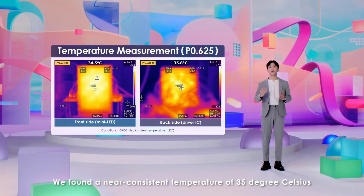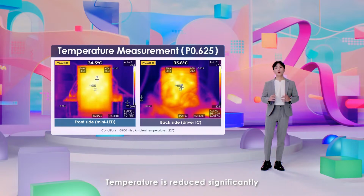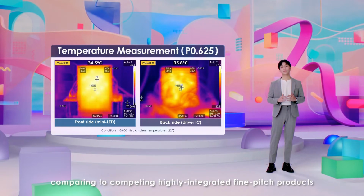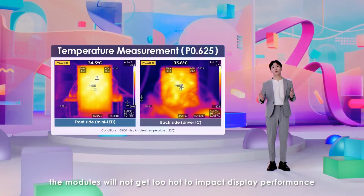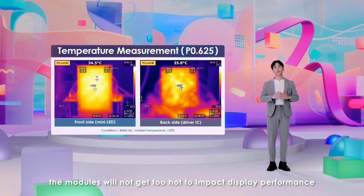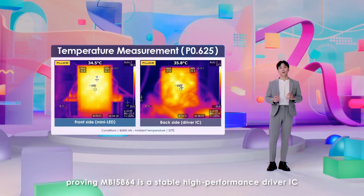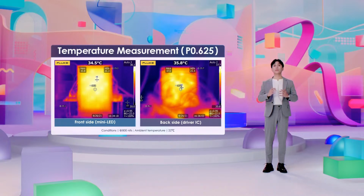Lastly, we measured the temperatures of the P0.625 module with an all-white image at 800 nits. We found a near consistent temperature of 35 degrees Celsius with the front and back ICs. Temperature is reduced significantly comparing to competing highly integrated fine-pitch products. This means with MBI 5864, the modules will not get too hot to impact display performance, such as cyan blocks or color shift, proving MBI 5864 is a stable, high-performance driver IC.